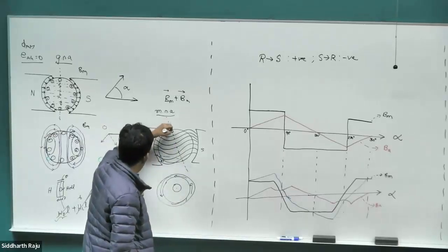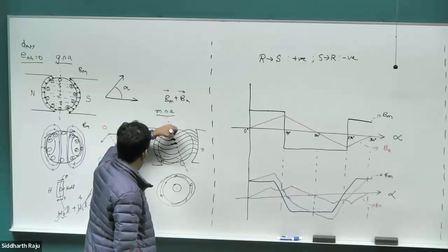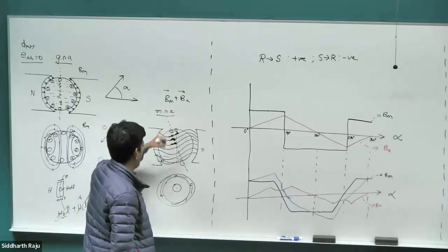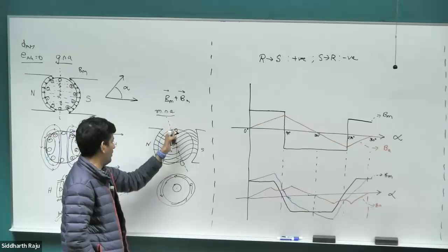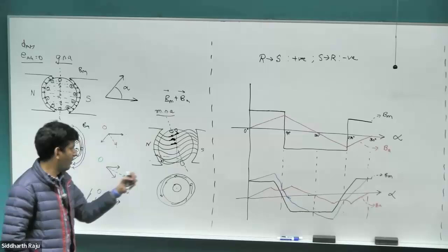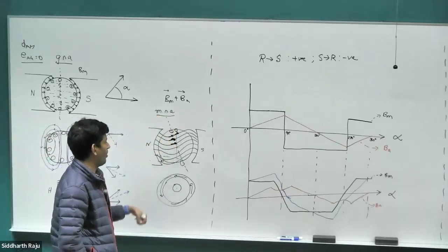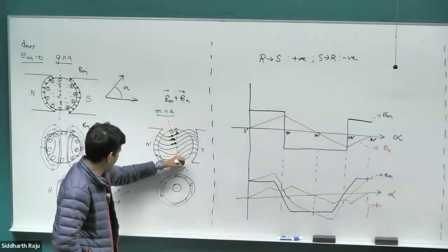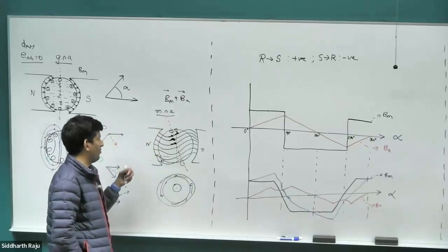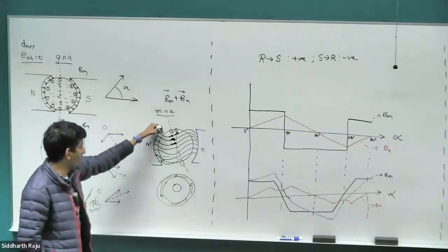So the coil here is the one that's perpendicular to the magnetic field. So this is where the magnetic field is perpendicular, no longer at this point. At this point, if you look at it, the magnetic field has some angle. So as the coil moves around 90 degrees, there's going to be a d phi by dt, because phi is the perpendicular component of magnetic field to the coil, right? So as this angle changes, the amount of B field that's perpendicular to the coil changes. But around this point, it is completely perpendicular. So slight variation in and around it would not lead to that much increase in the current, because phi is not varying too much around that point. So this is where the EMF will end up being 0.